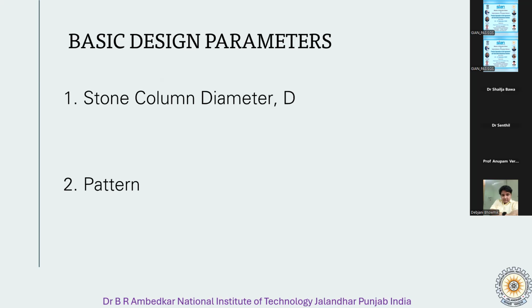Due to the lateral displacement of the stones during vibrations or ramming, the completed diameter of the hole is always greater than the initial diameter of the probe. Because in softer soil more displacement can be there, so the diameter is always more. And how much more depends upon the undrained shear strength, stone size, characteristic of the vibratory probe or rammer used, and the construction method.